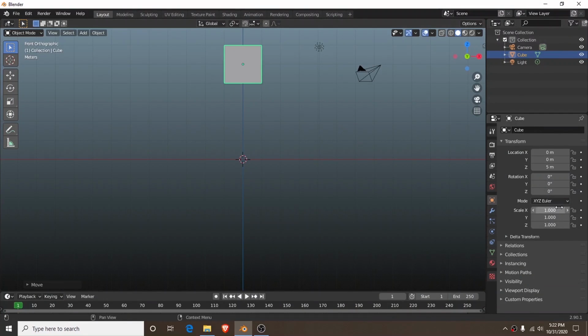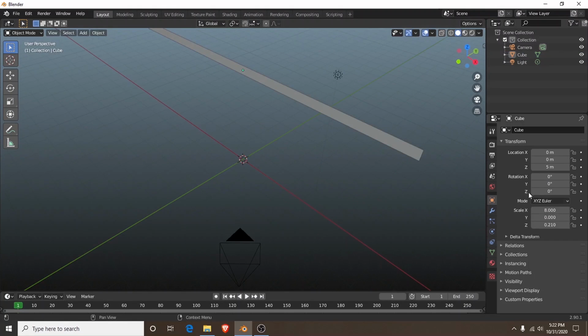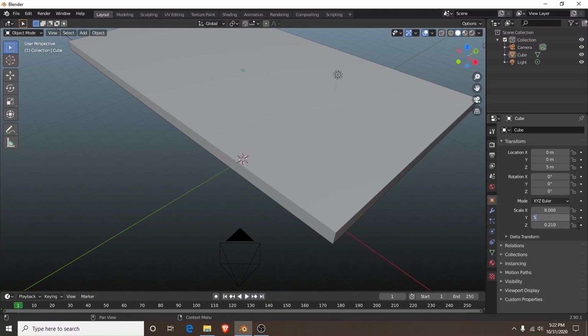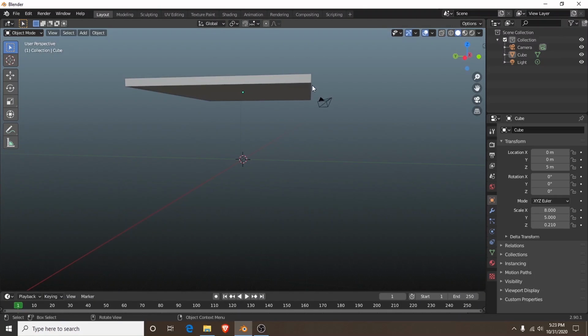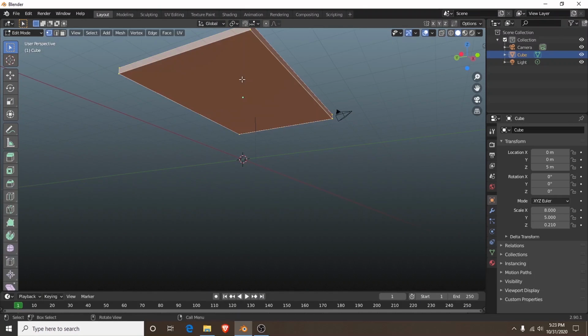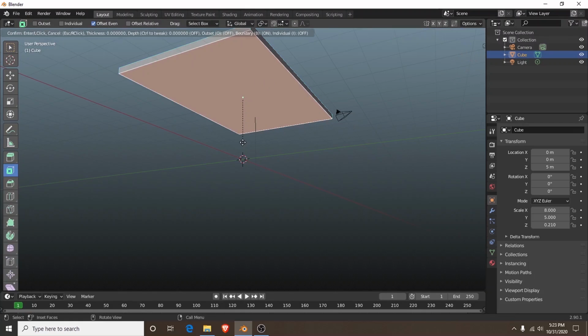As usual, when you start up Blender you should notice a simple cube. That's going to be the base for our table. I scaled it up to match our table's length and width. Increase the scale on the X and Y axis. Once that's completed, let's add another face to the bottom of the table so that we can extrude legs for our table. Simply go into edit mode, select the bottom face, and use the inset faces tool to add a face.